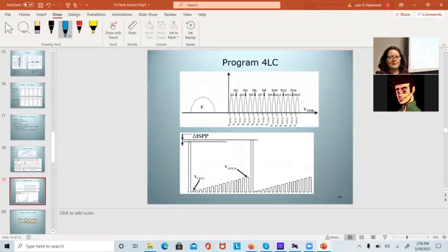If I want to program a 4-level cell, I need much better accuracy. I need to control the width of that threshold, make sure there's no overlap in here. So generally what I do, and the program and the pass disturbs are going to increase the threshold voltage. So probably the best idea is to program and verify at the lower edge of what's acceptable and let all the disturbs later on shift some of those threshold voltages up.